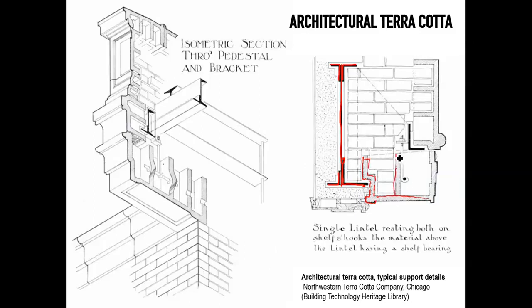It also has a rib here, and it's becoming basically a reveal of a window, and it's building up a bit of depth in the system. You can see there's an infill of bricks also. But from this edge beam, what's visible here is a gusset plate that is used to support another steel angle in this position.